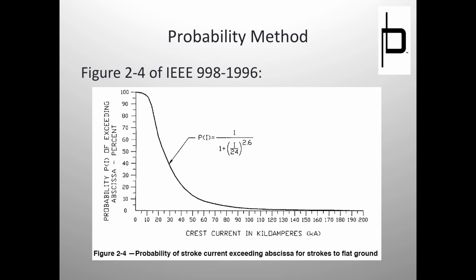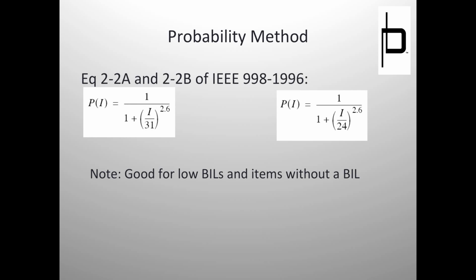I'll use that and roll the sphere around the substation, and say, okay, you're protected against 99% of strikes, or whatever. Everything that falls under the witches' hats, everything that falls under those zones of protection, is protected against 99% of strikes. Sounds fairly simple. Any questions about that? No.